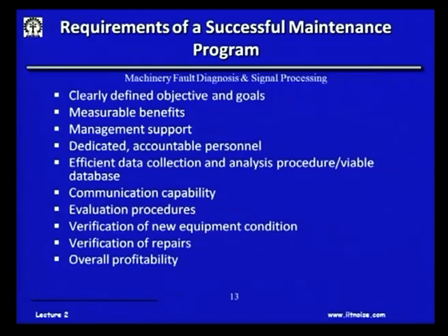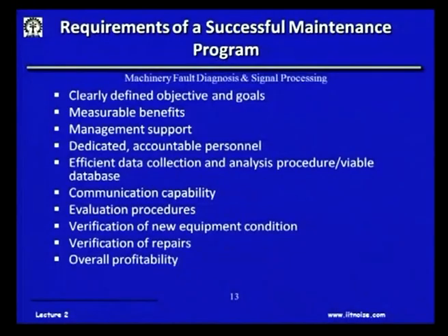So, to have a successful maintenance program, I need to have these conditions: dedicated manpower who understand the entire process, and good communication between the place where I am taking the data and where I am doing the analysis. I sample oil from one machine, and the technician on the other end thinks it is machine B, whereas you took the data from machine A. Labeling and data communication between the labs is very, very essential.